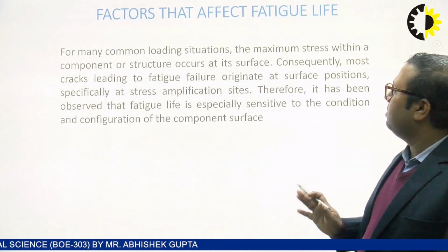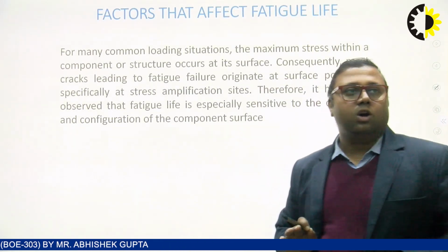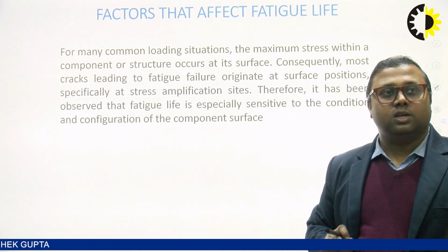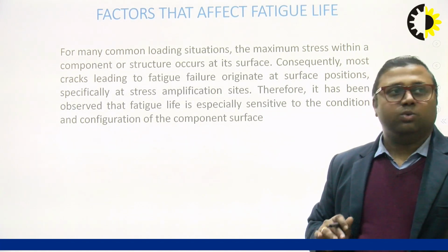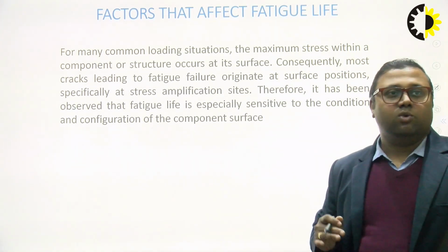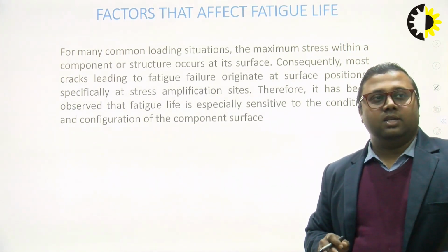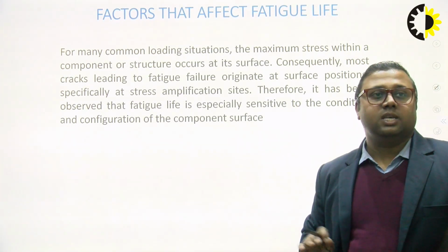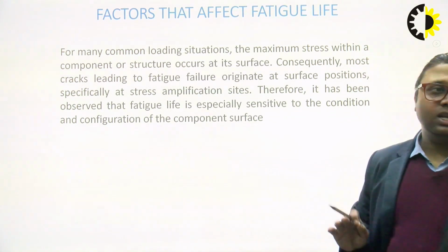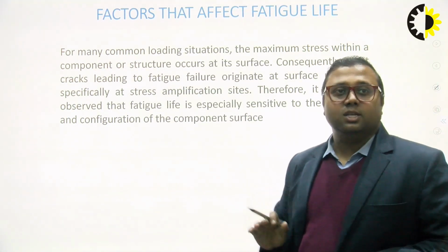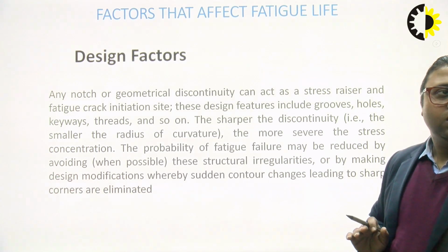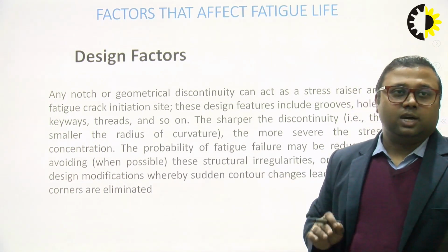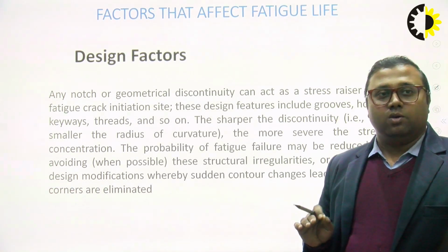So what are the factors which affect the fatigue life? For more common loading situations, the maximum stress within a component or structure occurs at the surface. Consequently, most cracks leading to fatigue failure originate at the surface where stress concentration is high, and it has been observed that fatigue life is especially sensitive to the configuration and the condition to which the component has been subjected.